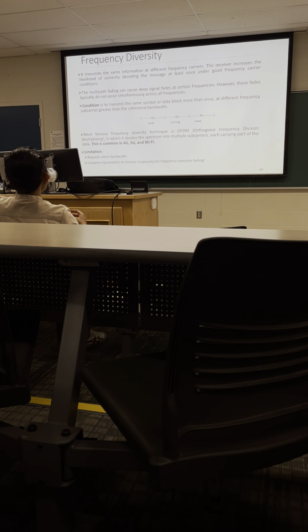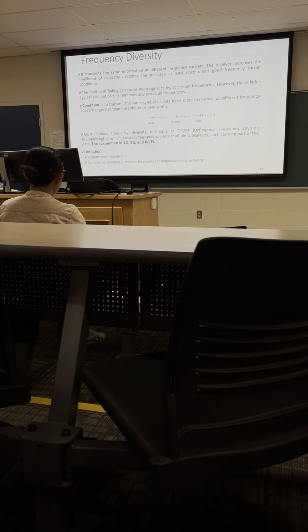This type is also commonly used, especially the concept of frequency diversity can be applied using OFDM. If you are working in the wireless communication field in research, maybe you are familiar with what is called orthogonal frequency division multiplexing. So the whole frequency, I divide it into orthogonal frequencies.